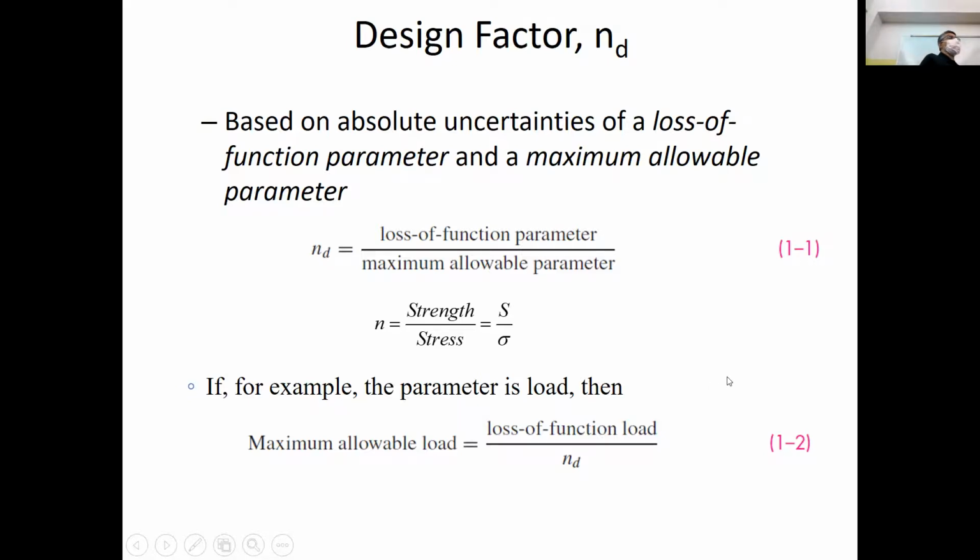As a designer, as an engineer, I know maybe my material is not perfect. Maybe my load is not perfectly aligned. So all these could lead to excessive stresses that I'm not accounting for. So where do I cover myself? Using this design factor. What are some typical values of design factor? Now, someone may say, oh, the higher the better. Is that always true?